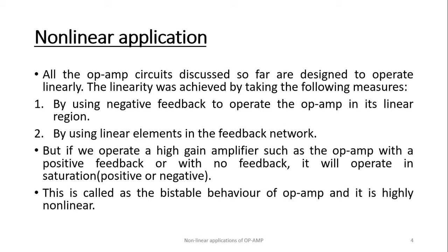Now, what do we mean by non-linear applications? All the op-amp circuits discussed so far are designed to operate linearly. The linearity is achieved by taking the following measures. The first one is using negative feedback to operate the op-amp in its linear region, and the second is using linear elements in the feedback network. Means these two measures are taken to create linearity.